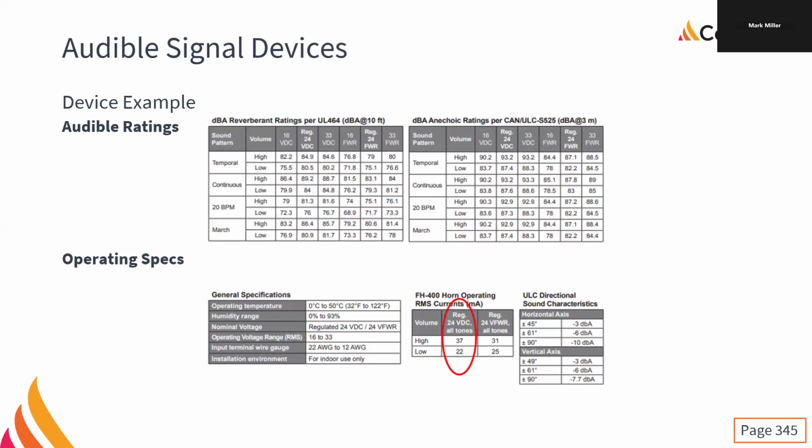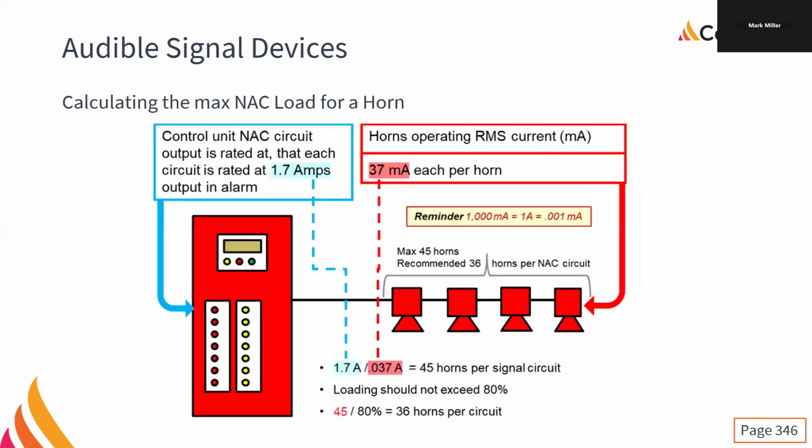If you were to take a horn, put it on continuous, and put it just off of a 24 volt rectifier, you would actually hear the voltage dropping on the rectification cycles. It actually makes an audible difference. So we rock with 24-volt DC because it needs to be as clean a voltage as possible so that the entire fire alarm system will work properly. Hope that made sense.